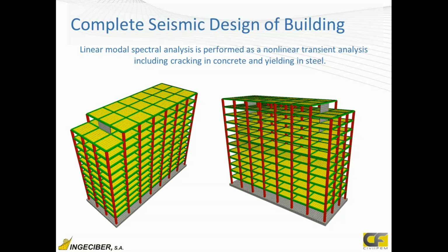We will see later, and study the typical failure points, failure nodes or connections in these structures. We will see that some parts of the model will be subjected to big forces, usually in the basement, the shear panels and some beams. They must be redesigned, so we can always perform a more detailed analysis in some parts.